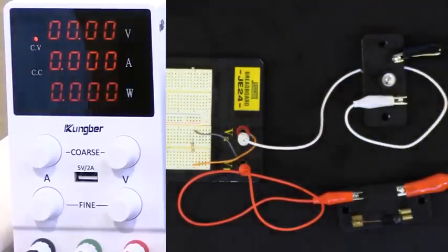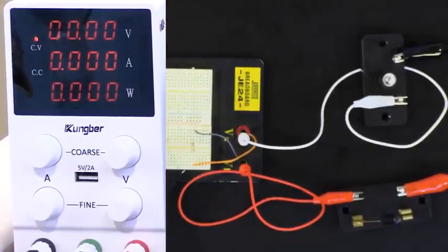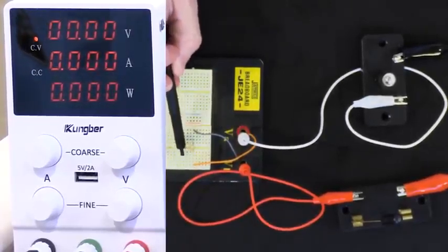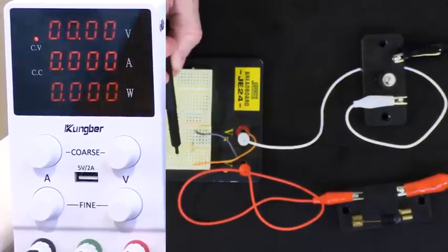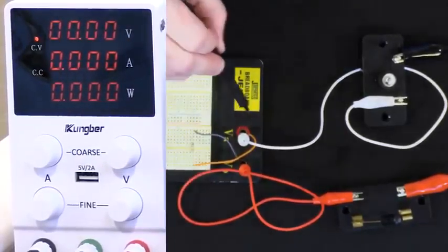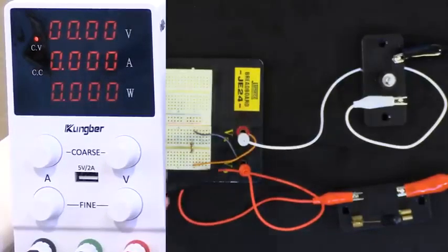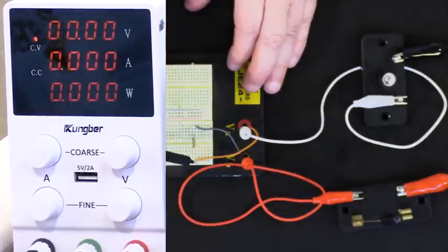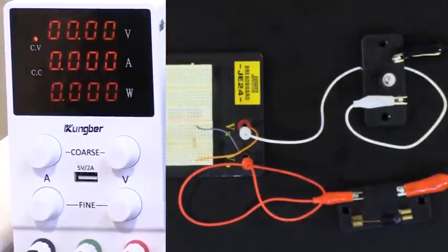The way this breadboard works here is the resistor is plugged into this line. When you see this line of little holes, all of these holes are physically connected together underneath. So there's a wire coming from this terminal up here, and there's a wire, you can see the gray one, going and plugged in here, and the resistor is plugged in the same row. So anytime you plug something into any one of these dots, they're all physically connected underneath.